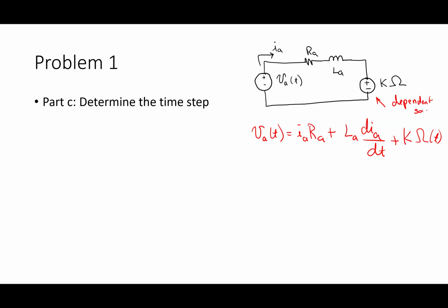All right. So you'll learn in later classes how to model this thing, but basically what it's saying is this is a circuit model for the motor. This V sub A is basically that H bridge or whatever that gets connected to this thing. So what's inside the motor is pretty simple. It's just some wire and then this voltage source, right? But the voltage source is a result of the physics going on inside the machine, basically a result of Faraday's law. And it's a model for what that system is actually doing.